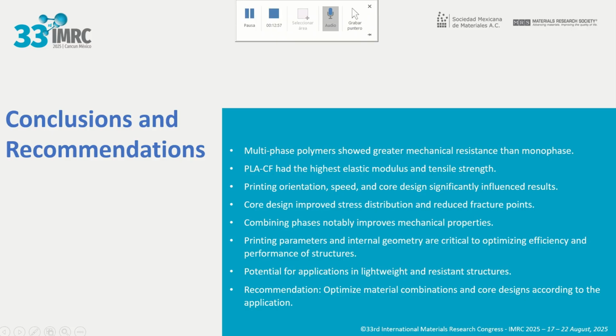Conclusion and recommendation. Finally, the main conclusions of the researchers are summarized, highlighting that multiphase polymers show better mechanical performance than single-phase ones. Multiphase polymers show greater mechanical resistance than monophase. PLA with carbon fiber has the highest elastic modulus and tensile strength.